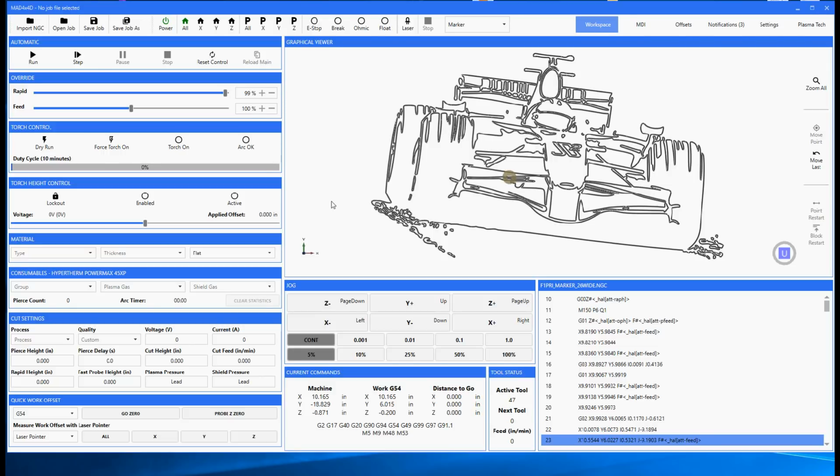It's telling you this is where I moved from where you started the cut height at. Now, where that becomes valuable is if you have a suspicion that for some reason torch height control is not actually active, you can look at that and you'll actually see the numbers change, and you can go, oh, well, heck, it's working. I've got another issue. Maybe I got the wrong consumables in it. Lord knows what could happen. Let's move on to another problem.